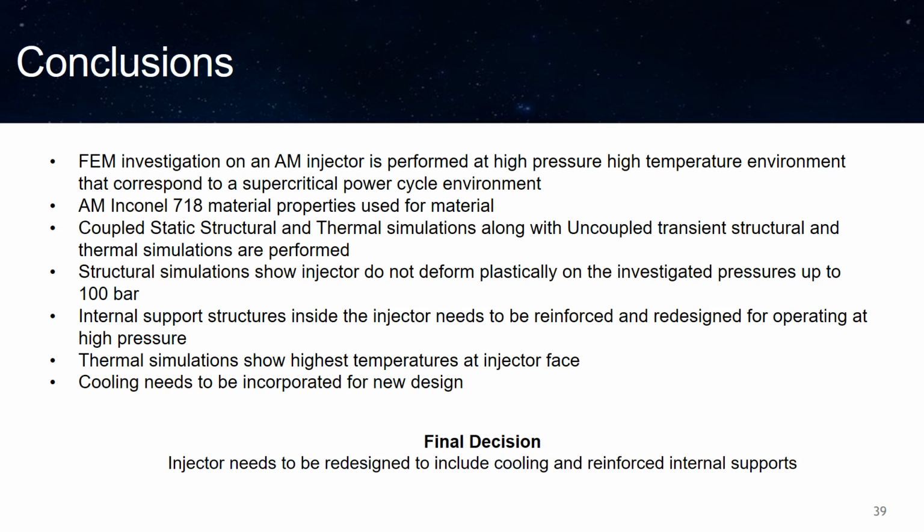The structural simulations showed that we can go up to 100 bar of pressure and not fail, however the internal support structures should be reinforced for safety, and redesigned for operating at high pressure. The thermal simulations show the highest temperature at the injector face, and we should be yielding due to those temperatures, so we need to implement a cooling design.